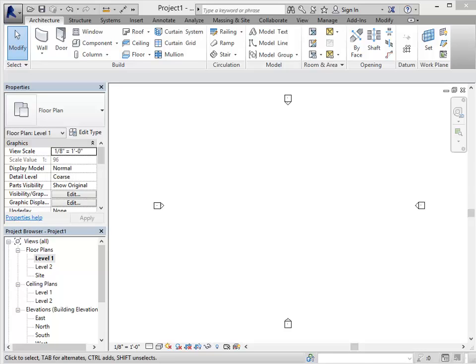To get started with building the first Revit model, we need to create some levels and we need to create a grid. A BIM model works parametrically. You create relationships between things, and we'll use these guidelines to help set the boundaries for walls and floors and roofs. That makes it so that if you ever want to change the height of a floor or something, you come back and you change the level lines, the walls and roofs and floors will go with it.